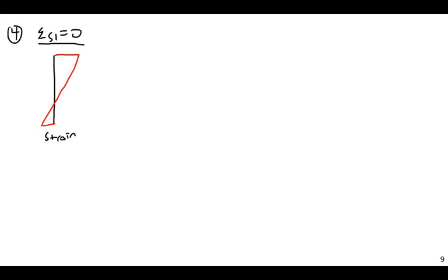And from the point of view of beams, this does seem odd. But when you start recalling that we not only have moment, but we also have axial force here, if you imagine the stress diagram from normal bending, and I then superimpose upon that a large compressive load, the compressive stress will tend to cancel out some of the tension stress, and it will shift the curve to the right, basically.